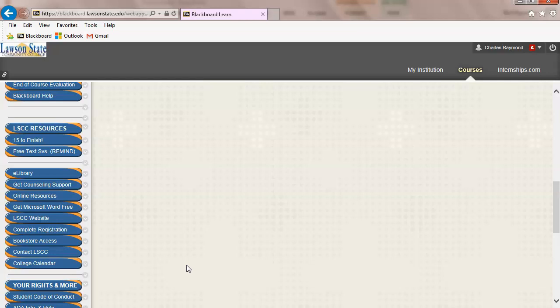What your thermostat usually has in it, it has an electronic circuit now, right? You understand? And it's got a span too, because if it didn't, it would be turning off and on all the time, right? So it gets up to a certain temperature, and then it turns off, and then it lets it do what? Some, right? Then it clicks back on, yeah. And what it's doing is picking up a relay.